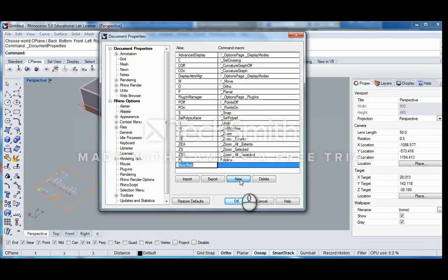Another one that we could do, extrude curve. We've been doing that fairly often. We could do EC, extrude curve. We could do extrude surface. Some of these also require a little bit of trial and error as it relates to the input on the macro end. Sometimes you need to not have a space here. You'll see if you try to run the command and it says it does not understand. I bet this is not going to work for these ones. So let's see. Okay, ES for extrude surface, EC for extrude curve, PL for polyline.